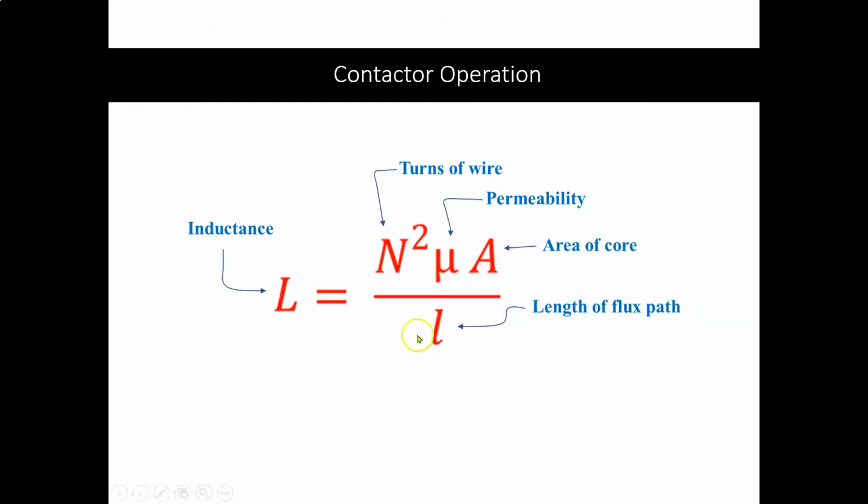Okay? Then you have inductance and reactance, and that's the effect of that current opposing your main current, and it's going to slow your current down. So when you get into phasor diagrams, you're going to see the effect of coils. It's going to slow your current down. Your voltage is going to get to its peak before the current does. Okay? All right. So we have inductance.